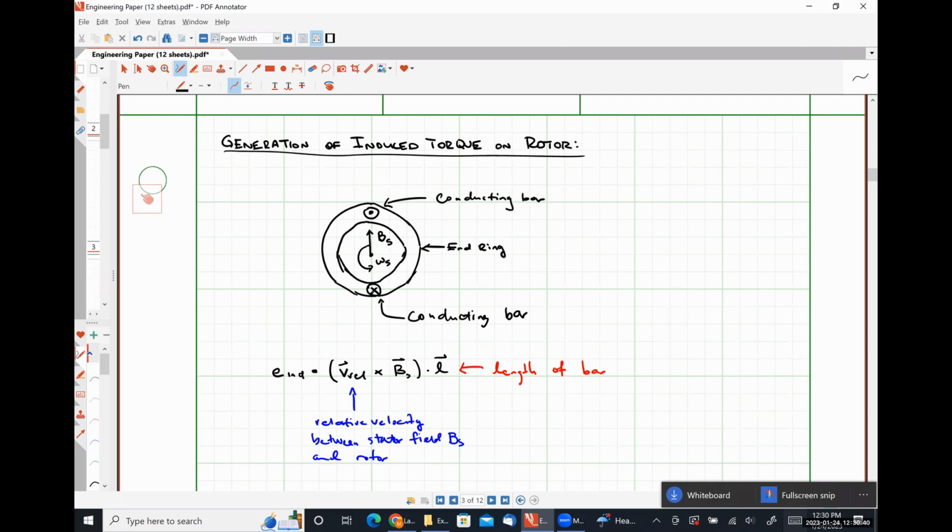As we have it right now, our stator flux is increasing because of the way that our thing is rotating. So our magnetic field generated by induction should be in the opposite direction to try to keep the overall flux small, which gives us a current in the directions that I've indicated here.